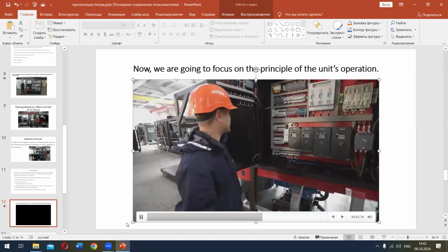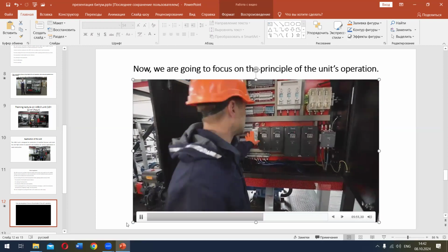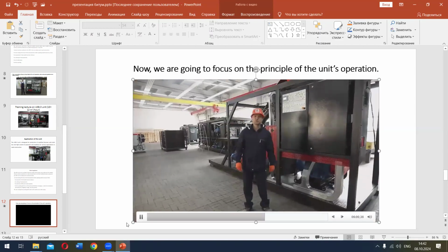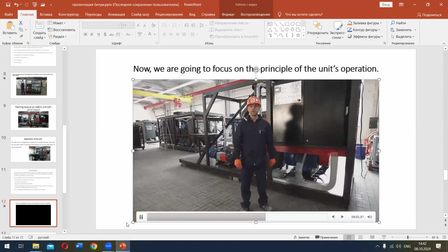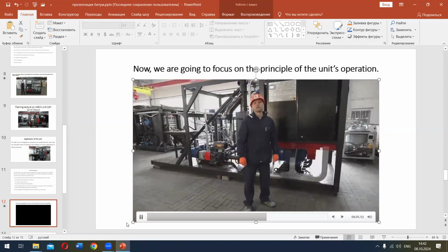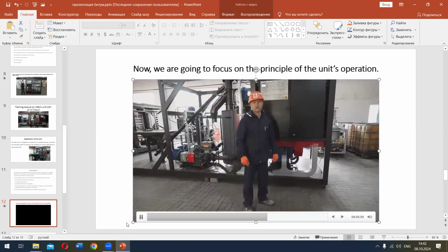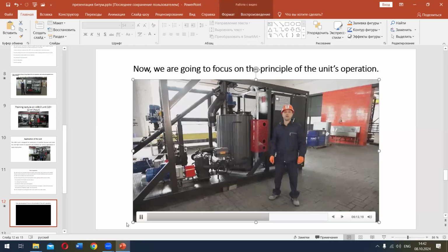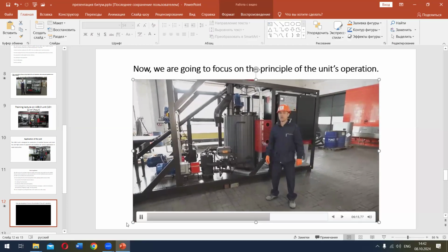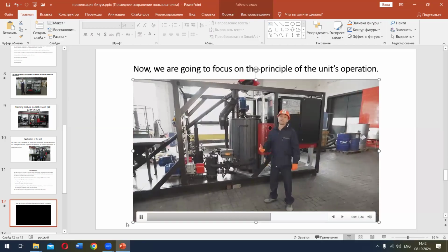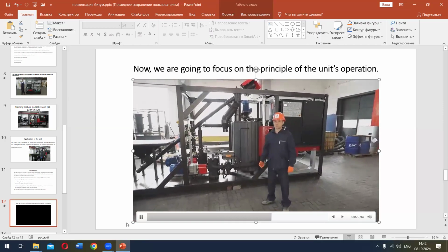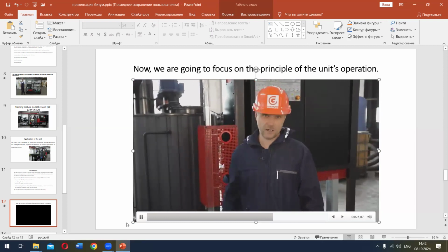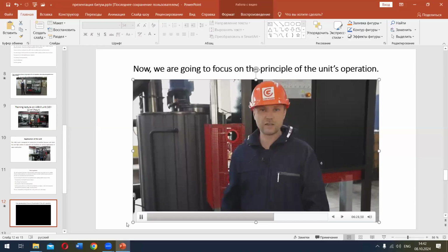The power circuits of the devices are equipped with circuit breakers, frequency converters, and a soft starter. The control system provides for operation of the unit in automatic and manual modes. The manual mode is used as a setup mode and mainly required for calibration of ingredients. The automatic mode of operation is the main mode, which includes the following submodes: warm-up, modification, additive modification, recirculation, reprocessing, and flushing. Certainly, the main mode is additive modification. All other modes are auxiliary, service ones.